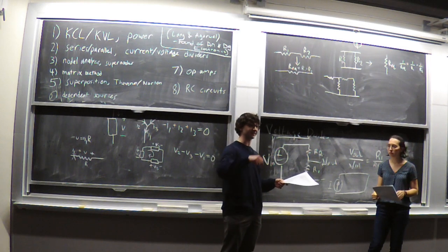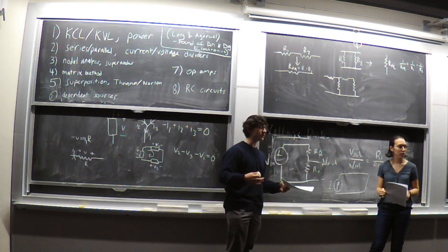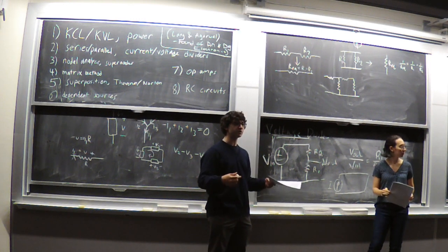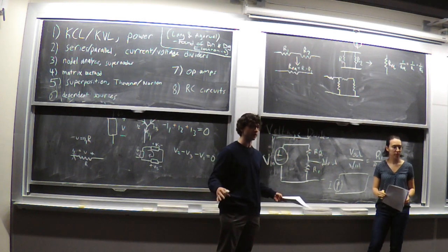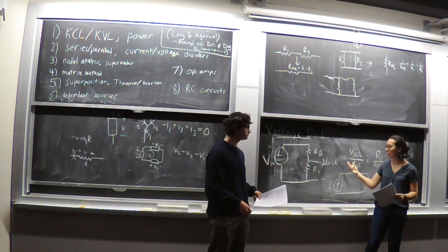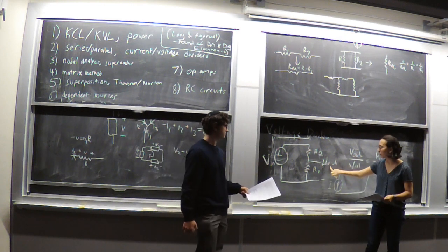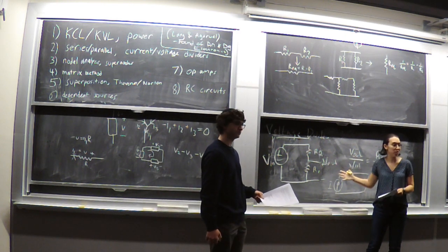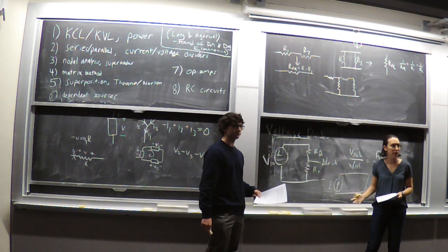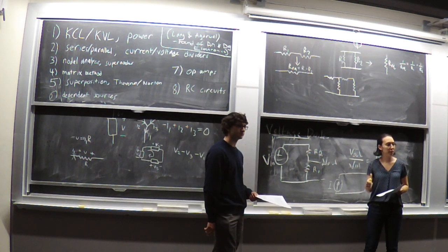Now, technically applying the scope probe is creating this whole circuit. We've designed scope probes, though, to draw almost no current so that it doesn't really disturb whatever it's measuring. So you can think of a scope probe as completing the circuit in some sense, but with a path of infinite resistance so that no current flows through there. So effectively, there is no path. Does that make sense?